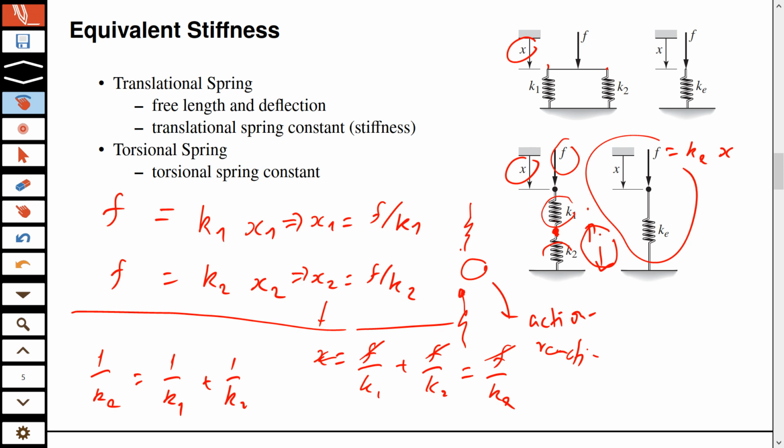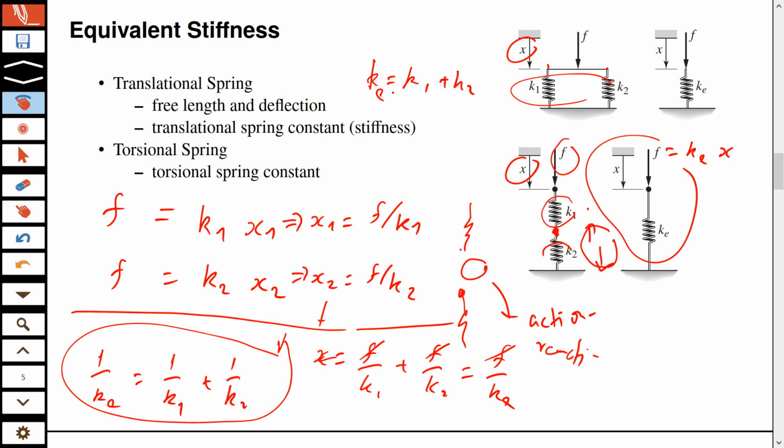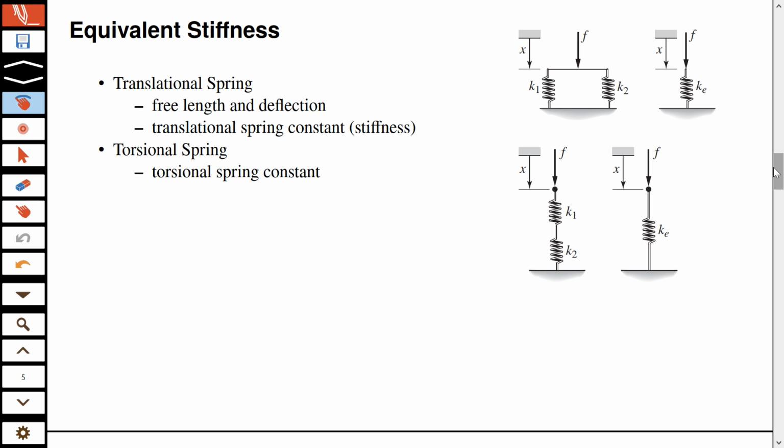तो अब ये आपको पैटर्न वही मिला कि when the springs are in series, their formula looks like the resistors in parallel. And when the springs are in parallel, their formula looks like the resistors in series. And I don't think this is difficult to remember, okay? Even if you forget the formula, you can still work it out. So, but what you need to remember, formula से ज़्यादा आपको ये पता होना चाहिए कि पैरेलल हम उनको तब कहते हैं जब x सेम हो, ये बहुत ज़रूरी है. सीरीज हम उनको कब कहते हैं जब उनका फोर्स कॉमन हो, because the same force is transmitted.